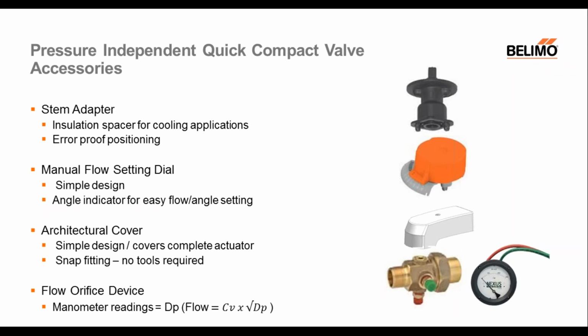It's also error-proof, so it can only go on the valve in one of two directions, and the actuator will fit directly on top of the spacer, and that goes on in the same manner. So there is no chance of making an error when you're putting in the spacer or when you're putting the actuator on the spacer.